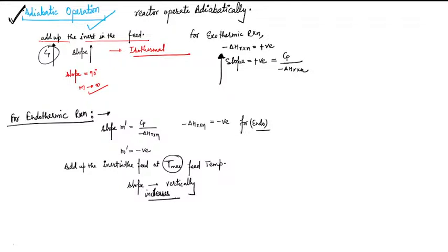The best path is this, because if inside the reactor the temperature profile is constant, then in this case the volume required will be minimum, because you already know the effect of the feed temperature on the volume. If anyone has a doubt, you can tell me fast. Now,